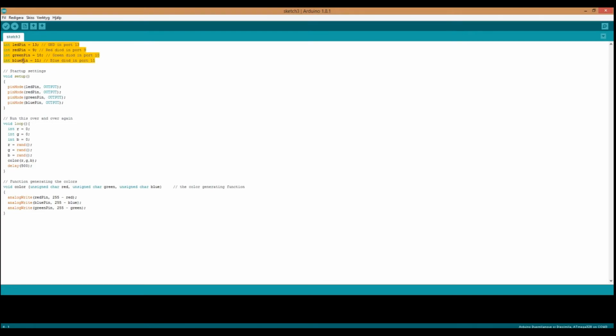the LED pins. Right now they only have a value, they don't really mean anything. But right here in setup, you choose the pin mode, number 9 is output. So you can just put your cable there and it's going to know that this is output. And then later on you're going to use that output for the loop and for the function.